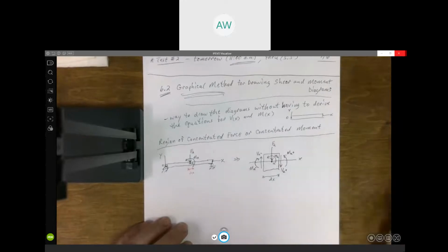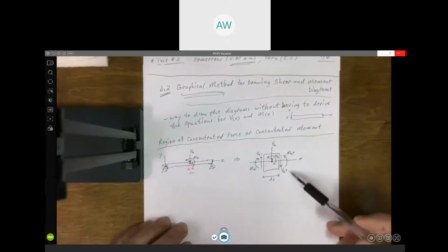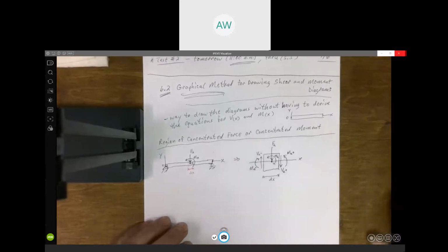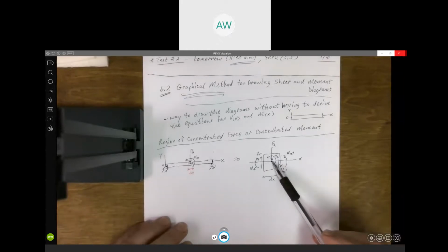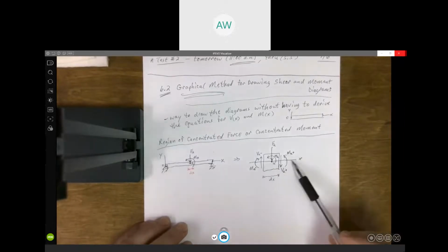The minus is just used to denote just before you get to point A, and anything with the plus subscript is denoting values just after point A. So what we want to see is the difference between the shear force before we reach this point where that concentrated force is applied compared to just after. What's the moment just before and just after? How does it change?